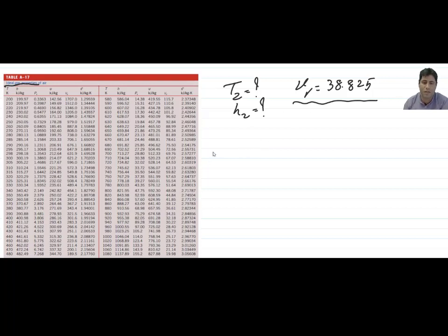It is a property which we can usually use to find the other thermodynamic properties. So let's see where we can find the VR or temperature in the table. VR which we have here is 38. You can see here temperature is increasing and VR is reducing. We start from 1,700 for temperature, and it is reducing here.